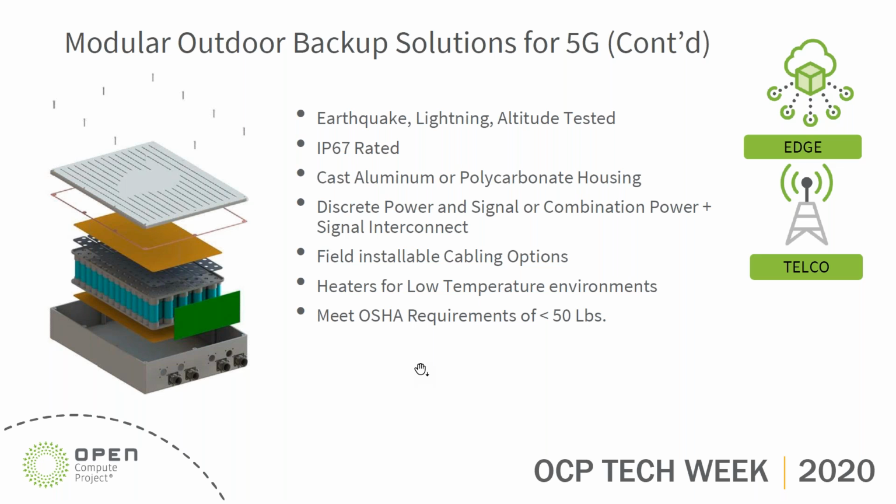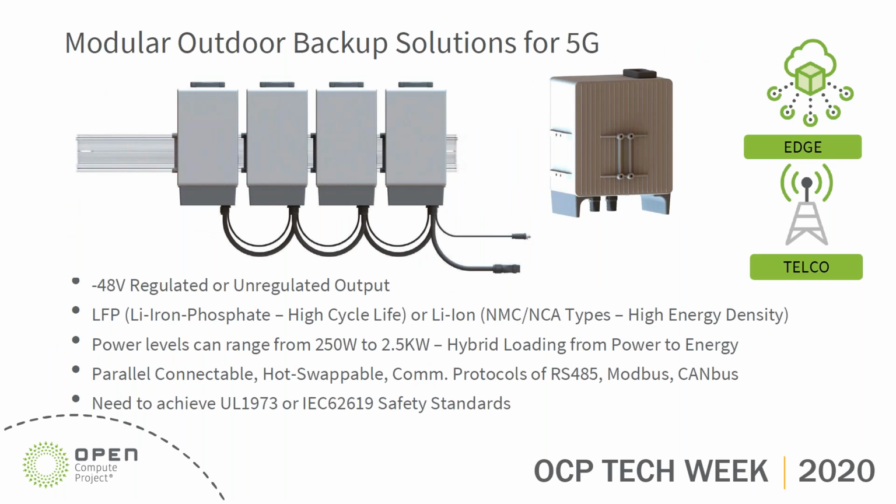And then as you can see, some O-ring sealing, and then the green is a PC board assembly that goes in there. One of the other things, and this is partially because I came from the connector industry, I get into the weeds and the details around that. These are not inexpensive batteries, and if you put a cheap connector on it and the connector fails, you now have an expensive paperweight. It's one of those areas of don't cheap out on the connector because it will affect the whole system. Clearly we need them to be IP67 rated, and I assume that somebody's putting them up on a tower wearing gloves, it's cold, and it really needs to be very, very easy to make the connection. Also, in one of the pictures, if I go back up, you'll see that there are legs. So even if somebody were to put this down on the ground, they're not going to hit the connectors and potentially damage them.